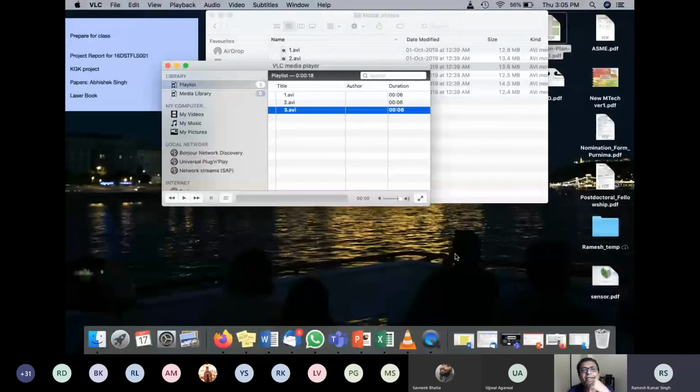This can be done for any system. This is just a free shaft, but if you have all the compliances, bearings, it will have different natural frequencies. And if you excite that natural frequency, in some cases it is more dangerous than the other. In some cases, there can be some twisting, there can be some bending. So it can be combined modes also.